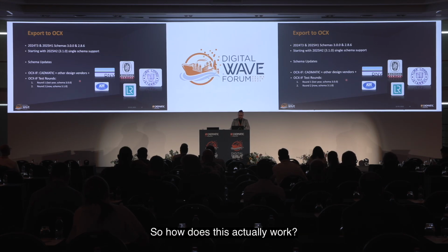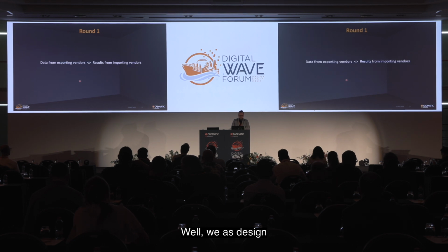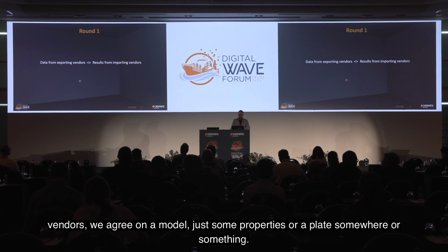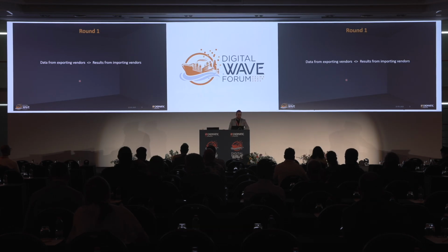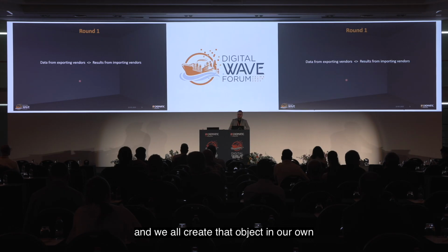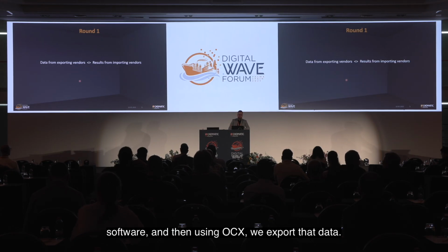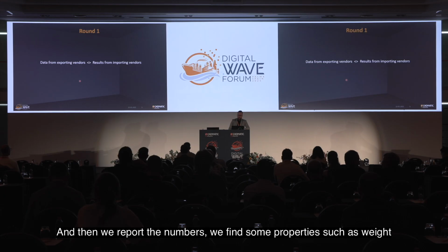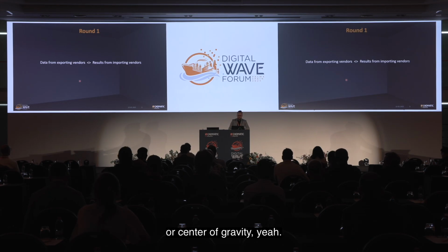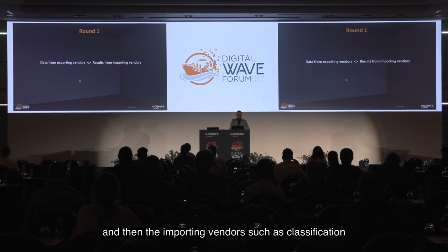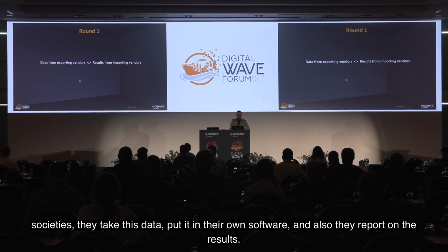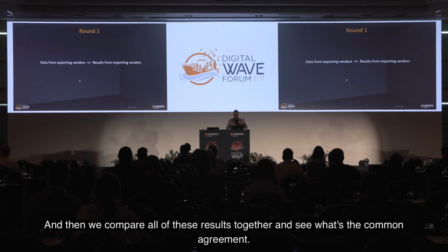So how does this actually work? Well, we as design vendors agree on a model, just some properties of a plate somewhere, and we all create that object in our own software. Then using OCX, we export that data and report the numbers we find, some properties such as weight or center of gravity. The importing vendors, such as classification societies, take this data, put it in their own software, and also report on the results.